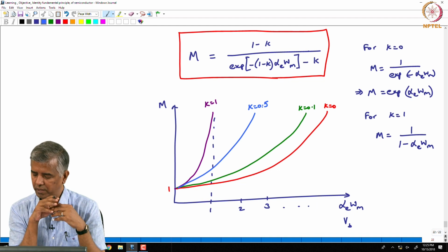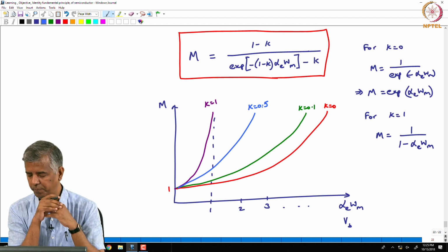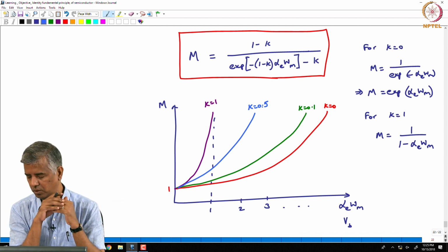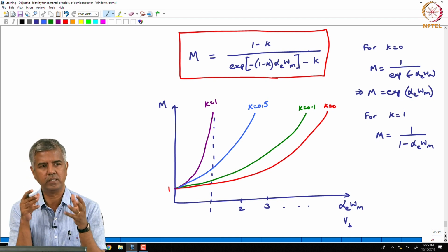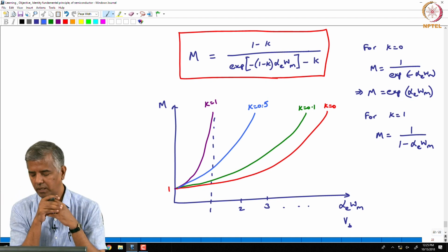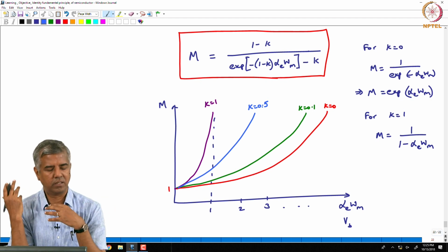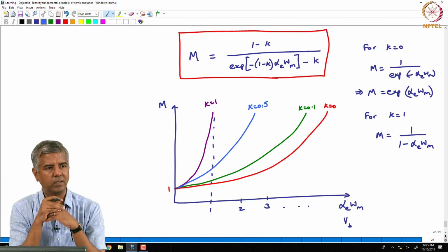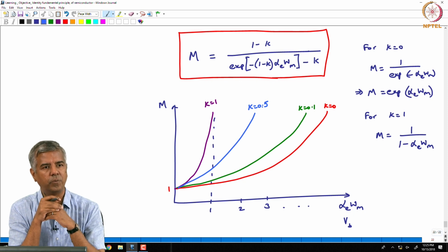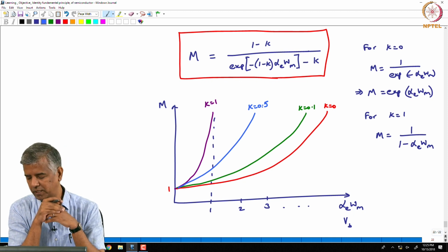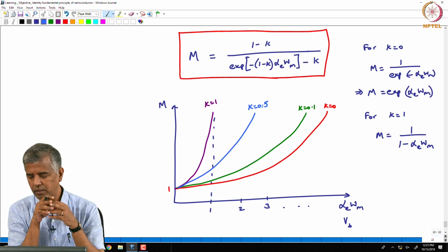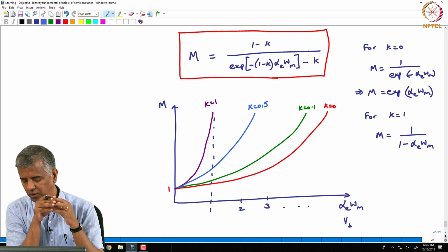Yes, indium gallium arsenide you can say has got higher impact ionization coefficient. So, even for low voltages it gives you much gain, but beyond a certain point you start triggering your holes also to provide the avalanche multiplication. So, that can become very noisy.